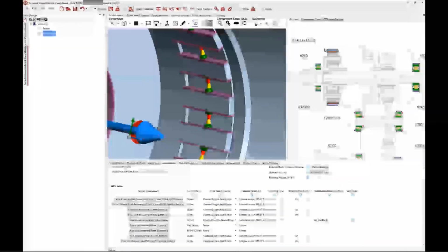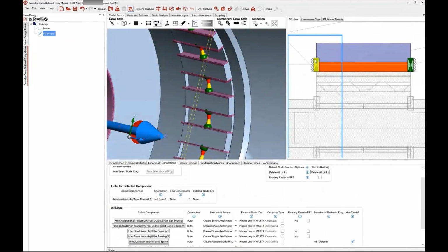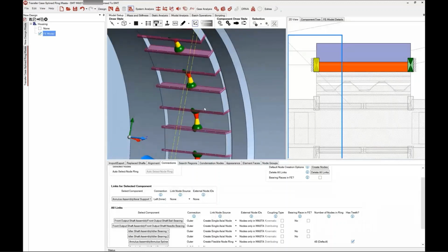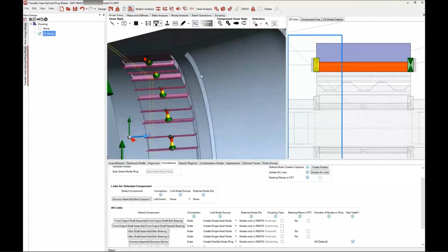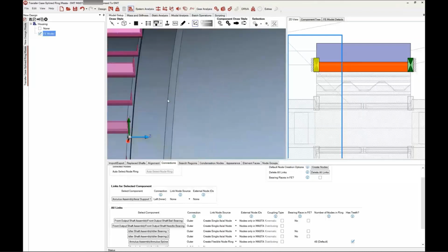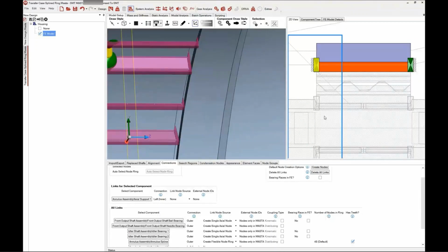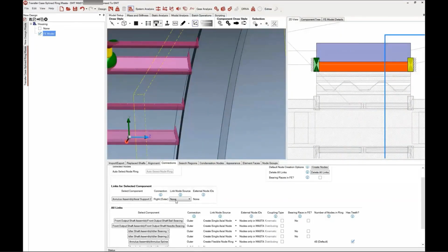Okay, and then the last thing we're going to want to do on the casing component before we perform the reduction is to set up these connections here. So, of course, we want to make sure that we have the correct stiffness specified. In my case, that means these axial clearance bearings. If you're not familiar with these, they're essentially methods of modeling clearances and connection points in your master model. So in this case, there's going to be an axial clearance either side. That's going to give it an axial stiffness because our spline is going to be able to slide otherwise, which is going to be, I think there's a groove which these are going to sit in. So there's one, kind of hard to see. There's one here and one on the other side, which I'm going to try and fit these in.